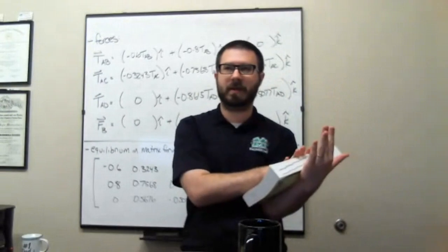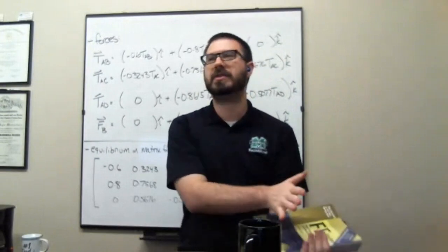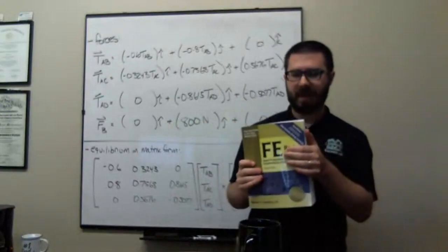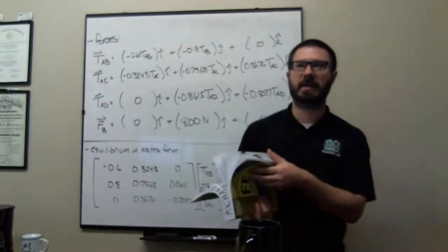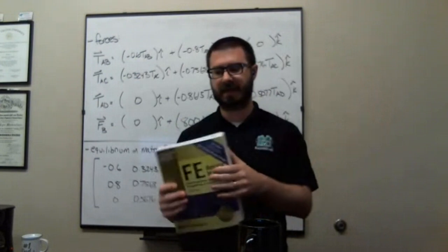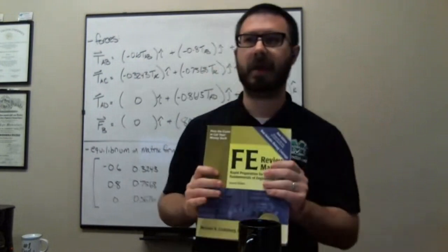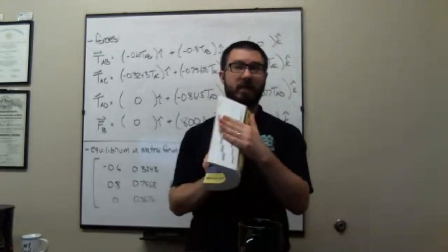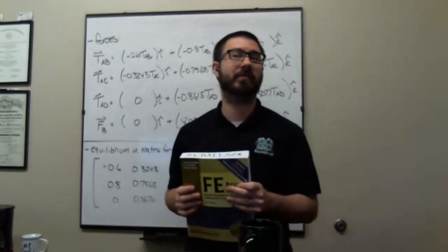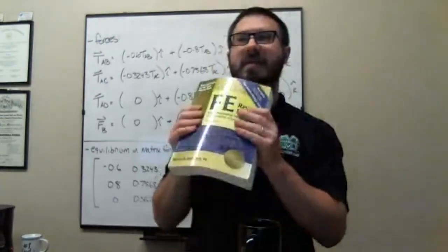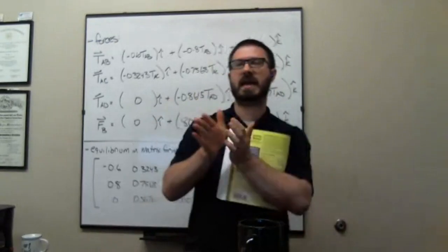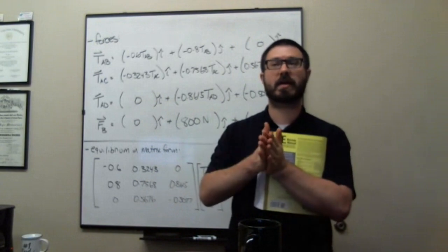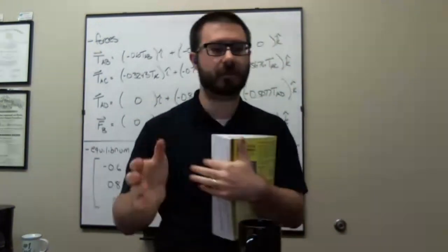There's shear developing in the beam, but the pages aren't resisting it because they're just going. So imagine if I took this book and I super glued all the pages together. I had oodles and oodles of time, and I super glued the pages together. What would happen is I would essentially turn this book of a bunch of paper into basically a block of wood, because when I start bending it, the pages can't slide against one another, and now what we've got is a beam. We've got a beam that resists those shear forces.